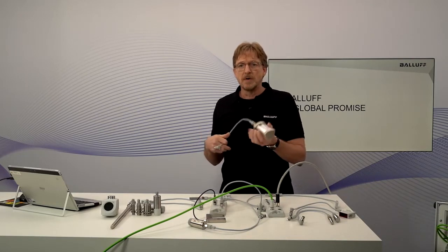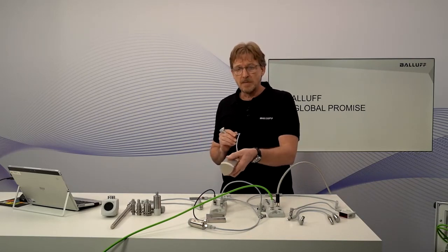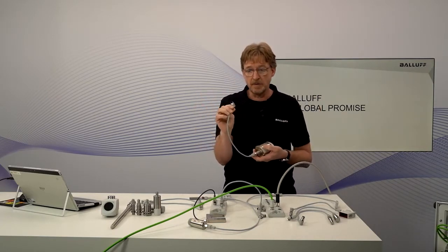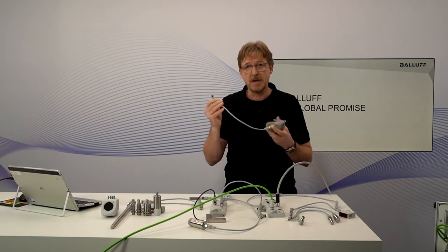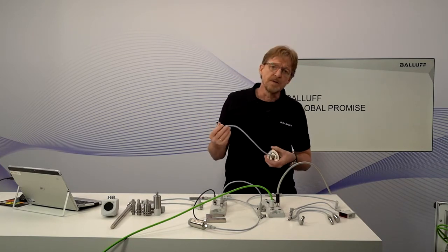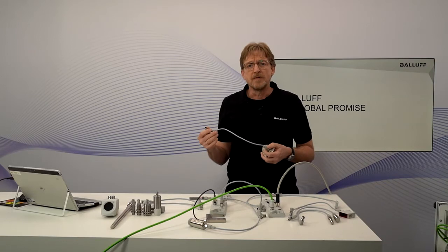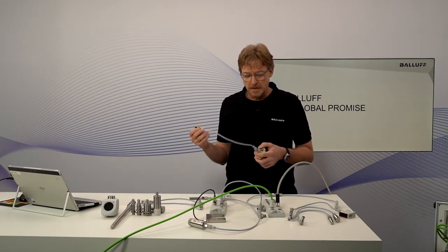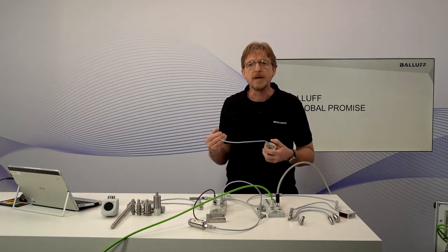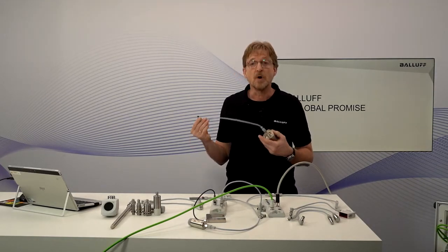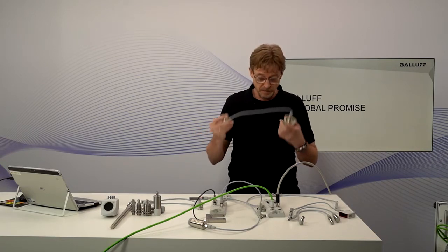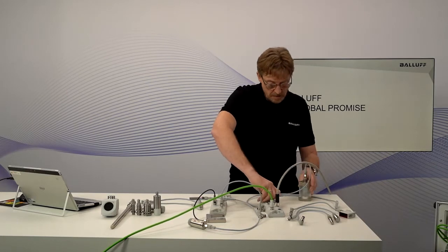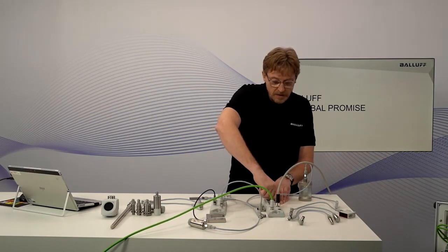The first device we are going to connect is this smart light. This is one type of the smart lights, and we will connect this with an M12 connector, 4 pins. Everything is an M12 connector with 4 pins, and on these pins it's always the same. Pins 1 and 3 are the power supply, and pin 4 is always the communication. That means IO-Link. So we will connect the smart light to the first IO-Link port here.